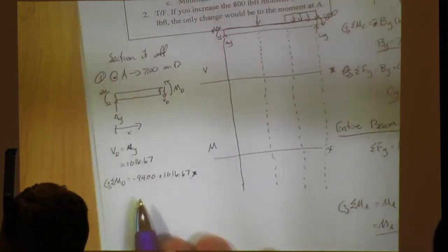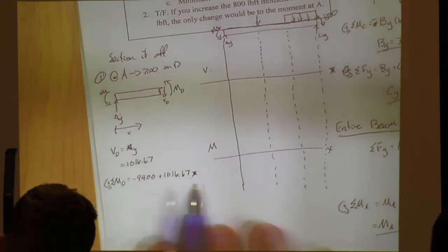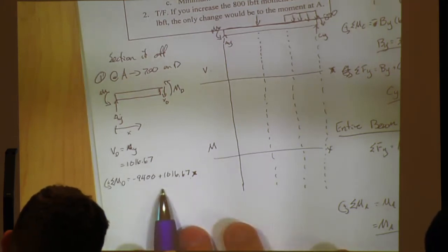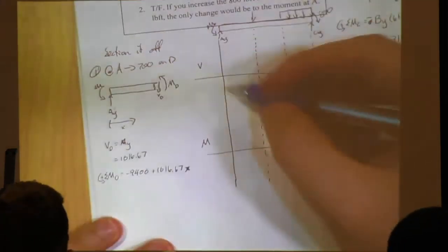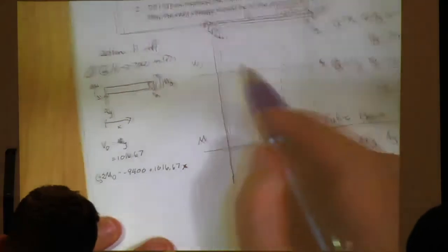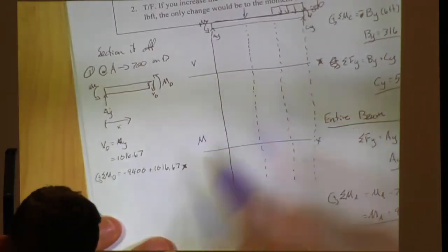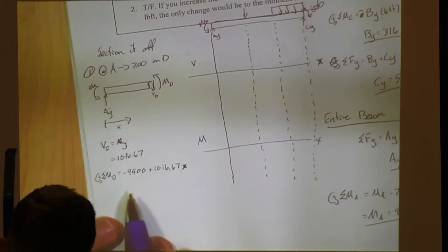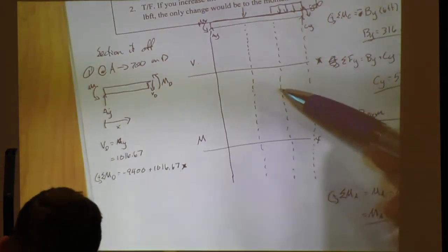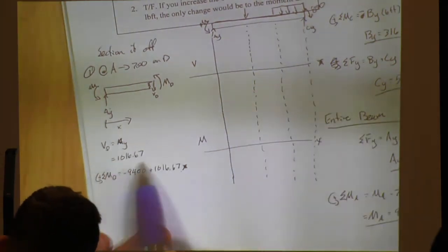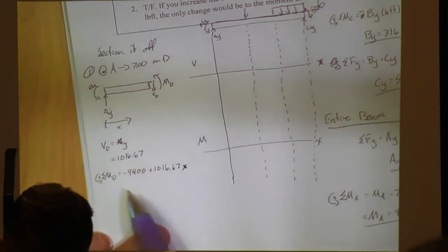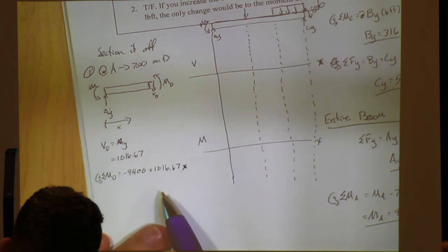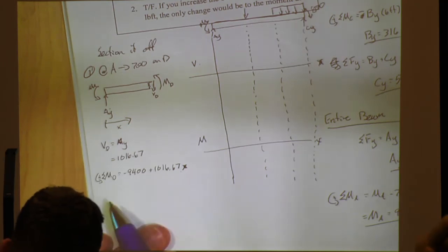Sort of. So when you're looking at this, what kind of equation is this? It's an equation of a line. So this equation of the line is going to dictate how this looks. This is just a reference to calculus, because this also gets into the integration method. You have your shear equation, and all you're doing is integrating this to get that, while taking into account the starting point at the reaction.